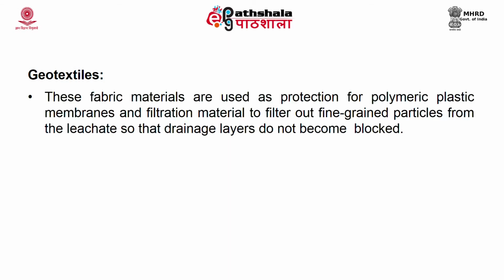Now, geotextile is a fabric material that is used as a protection for polymeric plastic membrane, and it is also used as a filtration material to filter out the fine grained particles which are generated from the waste and move along the leachate, so that the drainage or the leachate collection system are not choked or blocked.